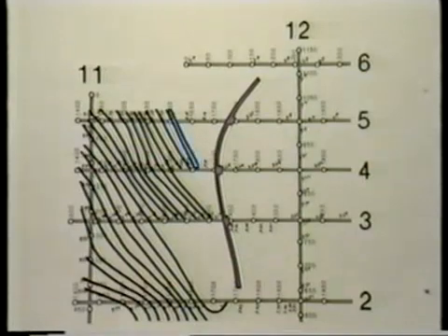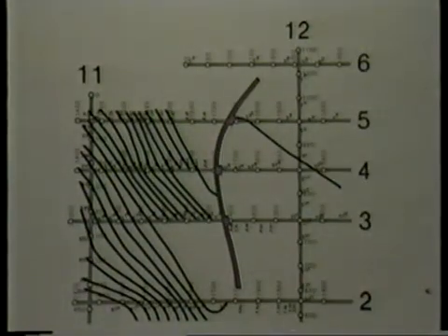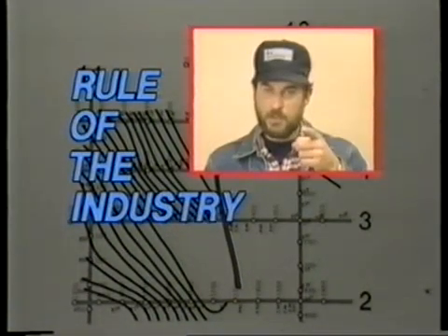Now that last one, 3.20 seconds, we can also find over here. So now we can take that contour up to the fault on both sides. Which illustrates one of the interpreter's golden rules. Contours which enter a fault must also emerge from the fault.